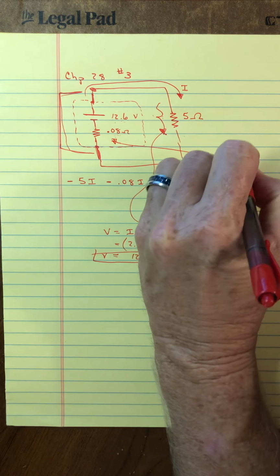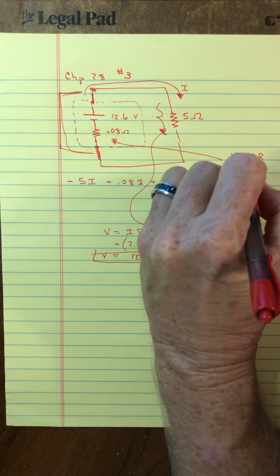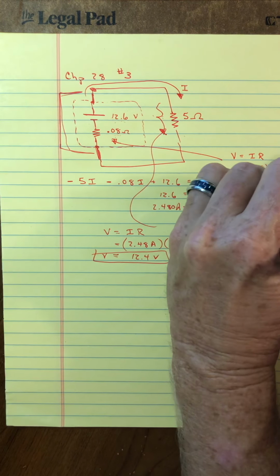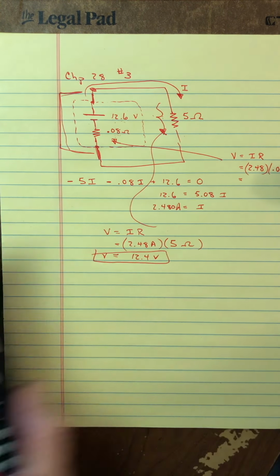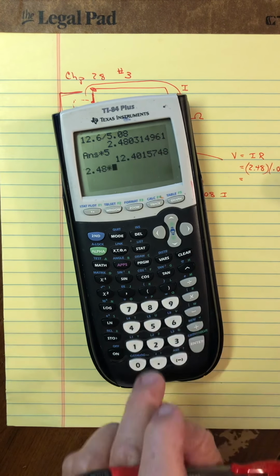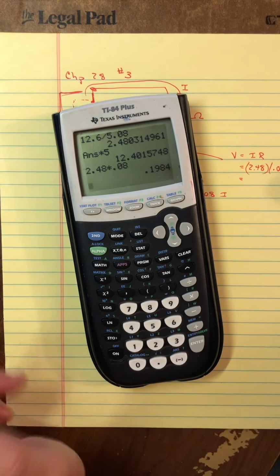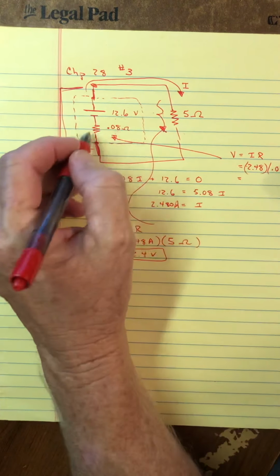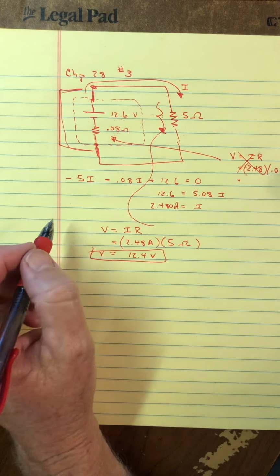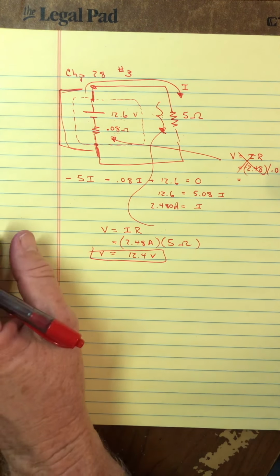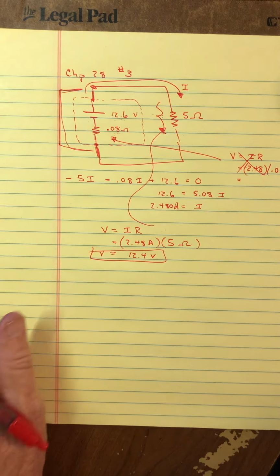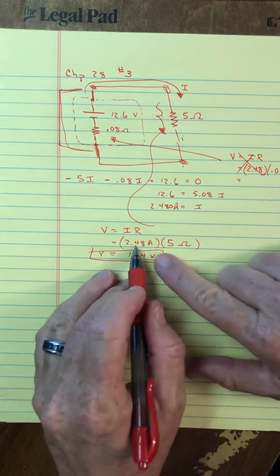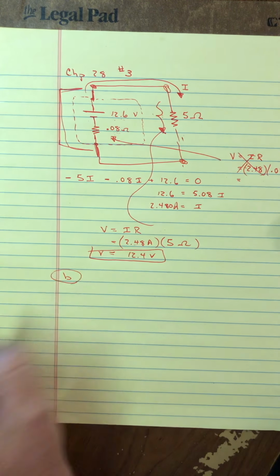And what we'll see, voltage equals IR. So if I take the current that goes through this battery and the resistance of that internal resistance, that should account for the 0.2 drop. There it is. Okay. So like I said, we could have done the drop and just subtracted it off, and then it would give, I think, a better picture of what we mean by a drop in a terminal voltage. But this was just so easy. Calculate the actual voltage across them by just taking the current times the resistance.